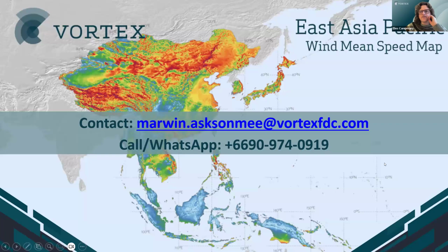Unless you have 30 years of data and you perform a Gumbel fitting with these observations, you cannot get a VREF. Even then, how you perform this Gumbel fitting could be different from one user to another, even though there is an exact definition, and it can fluctuate a lot if you change one of these 30 points of yearly maximums. So it's very difficult to validate the extreme wind VREF between model and observation. Yeah, thank you.